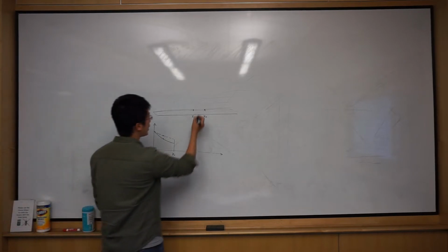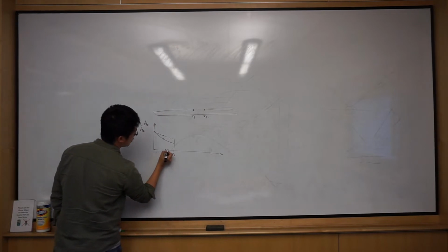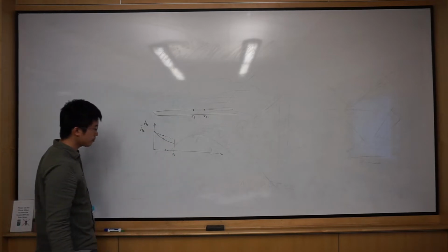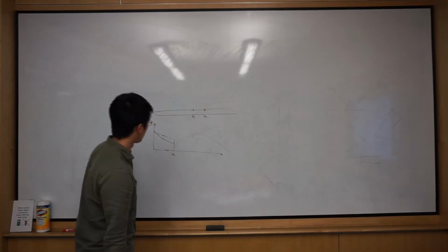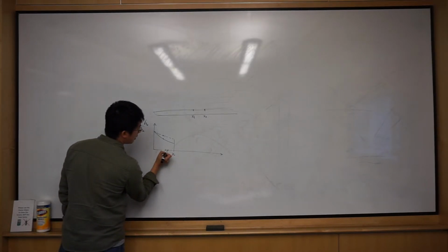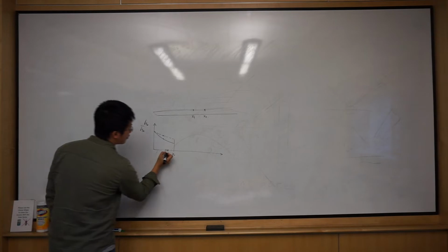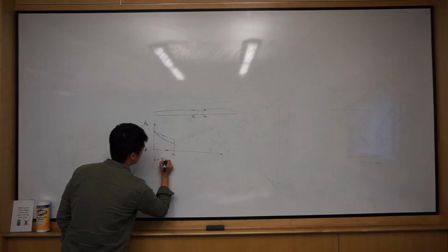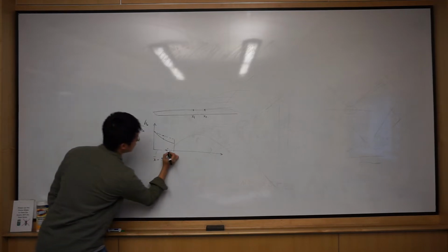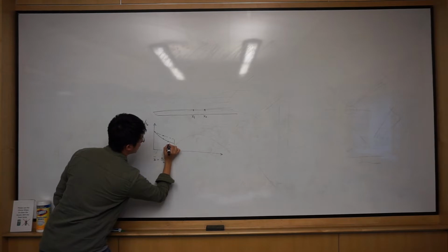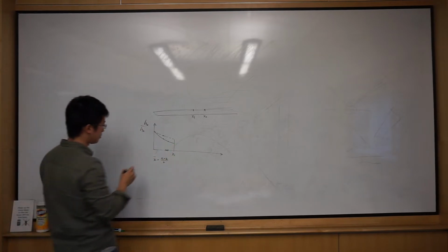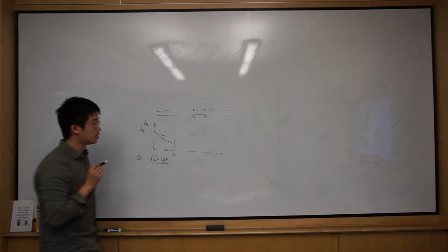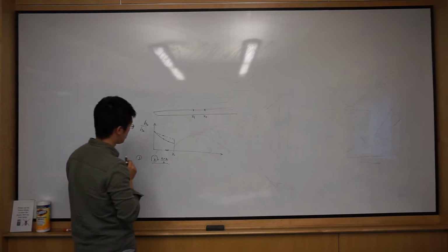To evaluate a small segment, let's say x1 and x2 are here and here, we have three different ideas. One is to find the coefficient at the average location. We do this, and by doing this, we are evaluating this point. Okay? Calculate this one and plug this number into the local convection coefficient.